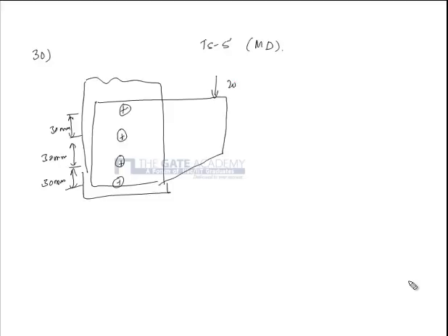The load applied is 20 kilonewton, and it's an eccentric loading, so the distance from the line of rivets is 80 mm. Now we are supposed to find the appropriate diameter of the rivet, knowing that the maximum shear stress in the rivet material is 140 MPa. The tau max is 140 MPa, and we are supposed to find the diameter of the rivet.